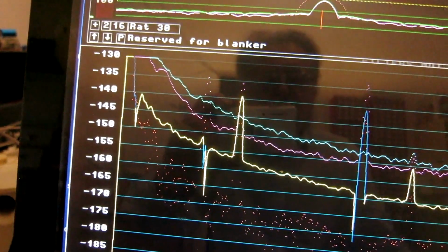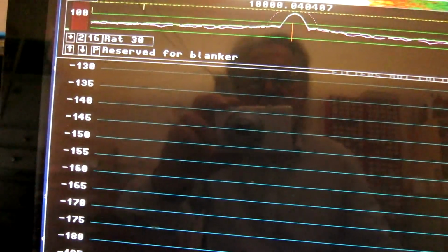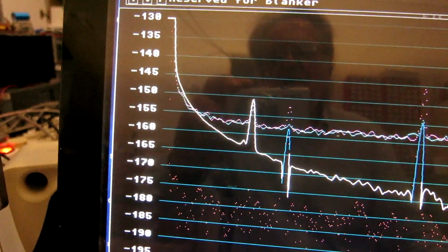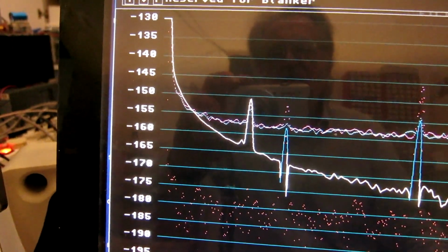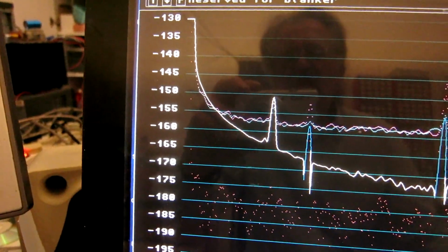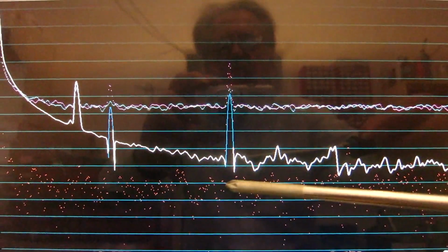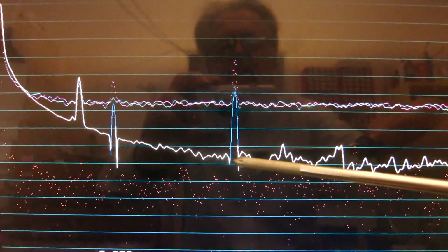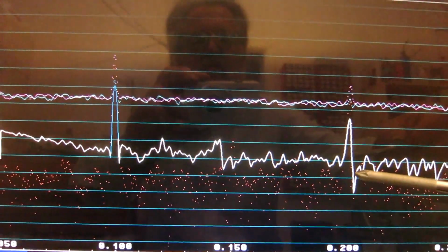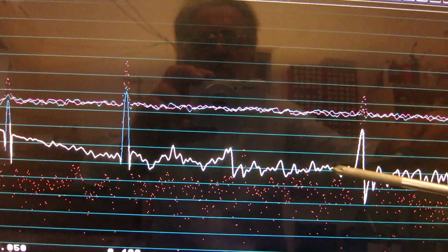So it's more interesting what happens on the amplitude noise, which comes here. And for the amplitude noise, signal to noise ratio is very good at low frequency, low offsets. But at 100 Hz, it is probably no longer okay. And I don't know whether there is a contribution from the termination.